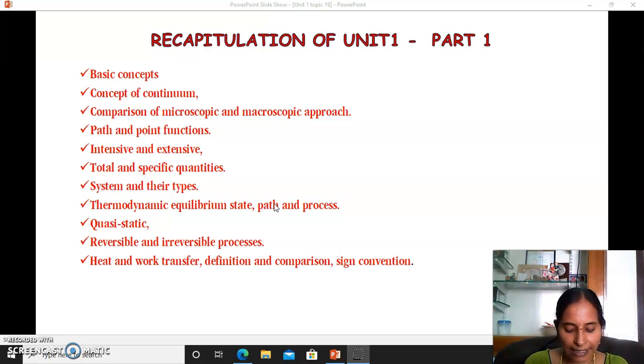Any process or series of processes whose end states are identical is called a cycle or a cyclic process. A system is said to be in thermodynamic equilibrium if it simultaneously satisfies the conditions of mechanical, thermal and chemical equilibrium. Phase refers to the quantity of matter which is homogeneous throughout in chemical and physical structure. A homogeneous system is of single phase, whereas a heterogeneous system consists of two or more phases.